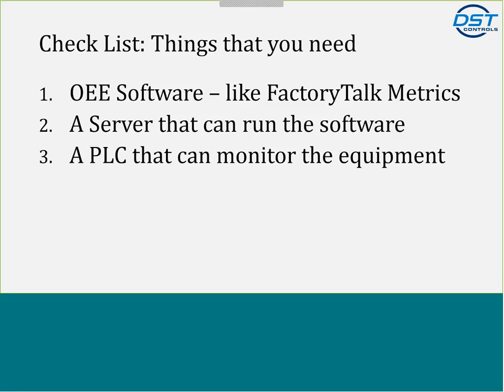Normally, we want to have a PLC that can monitor the equipment that we're interested in. Most modern manufacturing facilities already have the machines operated by PLCs, so we can add an additional purpose with that PLC just to do the monitoring and tie into those specific start-stop and running signals and a lot of other kinds of information that can be really valuable. If the equipment isn't running off of a PLC, then we can always put in sensors and hook that into some kind of very inexpensive PLC and then have that go into Metrics or whatever other software we're using.